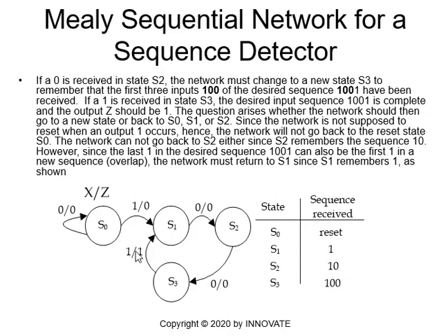Now, actually, I still have really a partial map, so I have to complete the map. To complete the map, every state must have two output arrows: one for x is 0 and one for x is 1. So I am done with S0. But S1 has only one output arrow, which is 0. What will happen in S1 if I receive a 1? For instance, S2 has one output arrow, which is 0. So what will happen if I receive 1, 0, 1 at S2?